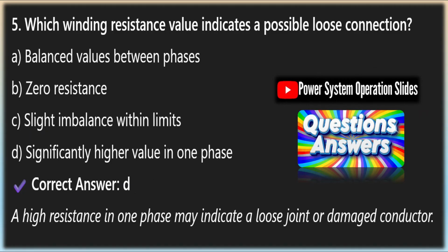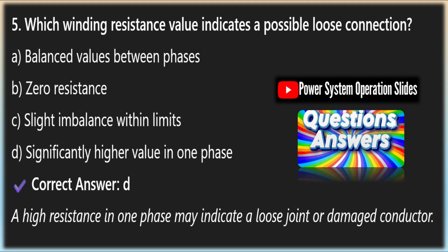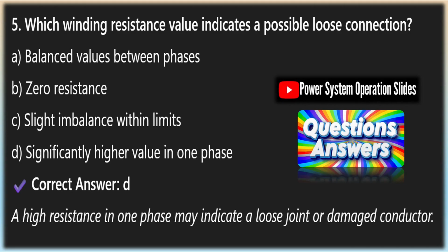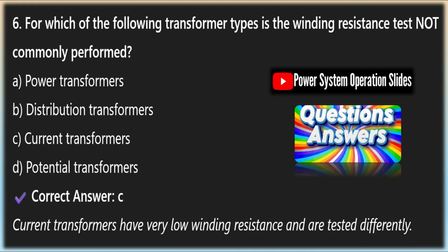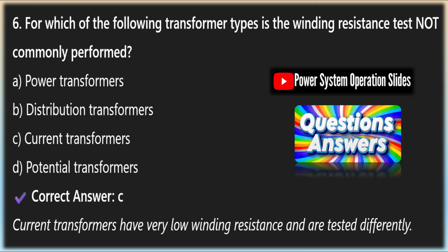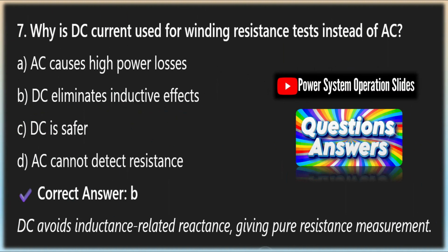Transformer winding resistance testing is recognized as a cornerstone diagnostic procedure in the realm of electrical power engineering. It serves to examine the integrity of internal winding coils within power transformers by verifying continuity and measuring the level of resistance. By comparing measured values against historical data or manufacturer information, one can detect subtle deviations that could compromise the transformer's capacity to carry load.